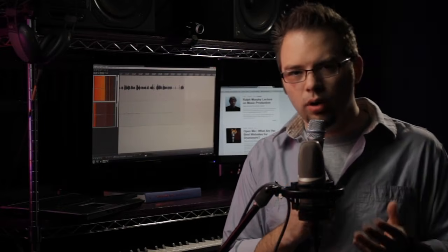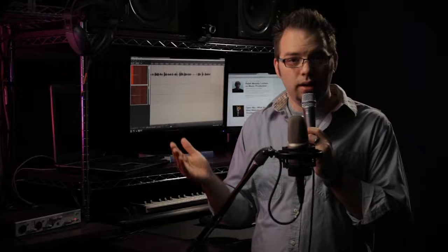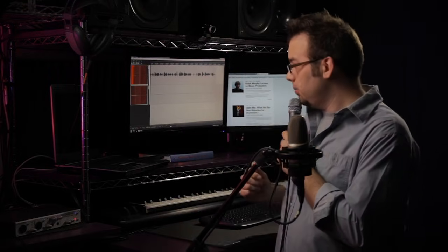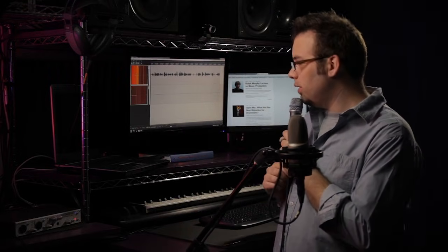It's also worth noting that this would only really work with a dynamic microphone because phantom power is not transmitted over line level inputs. So the only way to use a condenser in this type of situation is if you had a condenser with a battery. But using a line level input with a microphone is not a very good idea unless you run it through an external preamp. You can see that the level is not very usable.